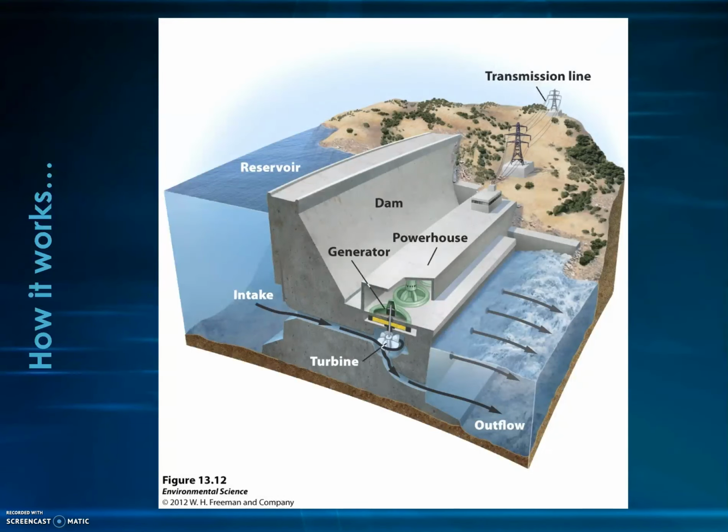How does hydroelectric power work? Well, the plant captures the kinetic energy of water and uses it to turn a turbine, which generates electricity. That energy depends on the flow rate or the vertical distance the water falls. The bigger the distance, the more potential it has. Again, we're always trying to turn this turbine, and so it is based on that flow rate.